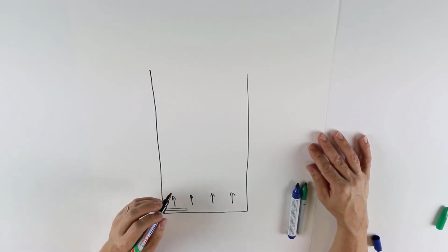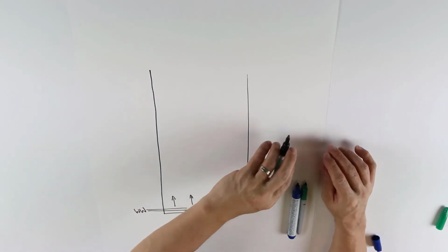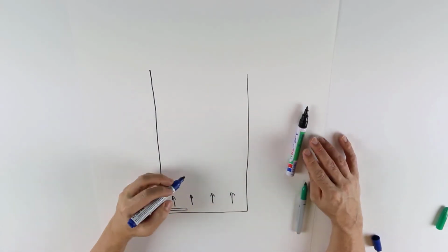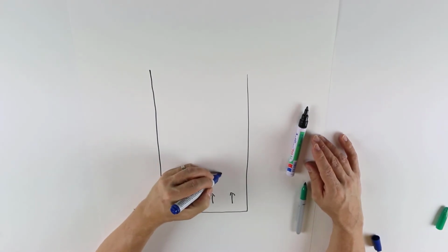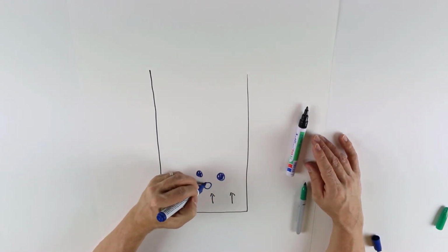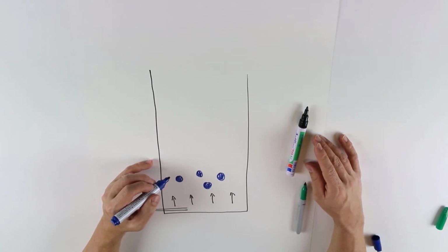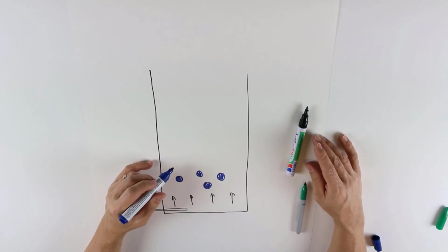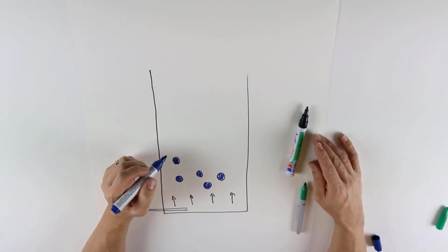Because the water goes up and gas is being formed, we get the formation of dense aggregates of biomass called granules. And so these granules are very dense assemblies of microorganisms that form your methane. And because they're so dense, rather than flocs which float, these dense granules stay inside the reactor, so they phase separate. You get a sludge blanket.